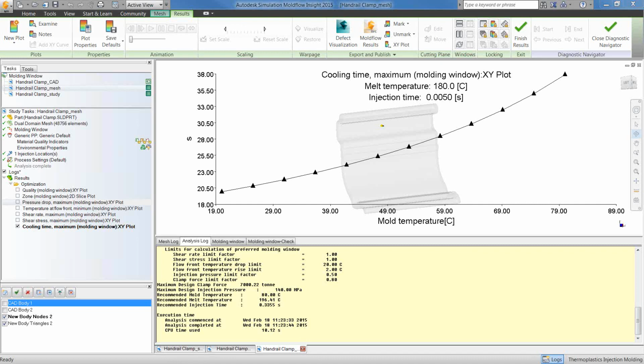Looked like Anik asked if we're able to use this with sequential valve gating, and looks like he answered that, but yeah, this is just used for injection cones only. The reason for that is what you're really doing is trying to find the optimal general area of placing that injection or feed system.